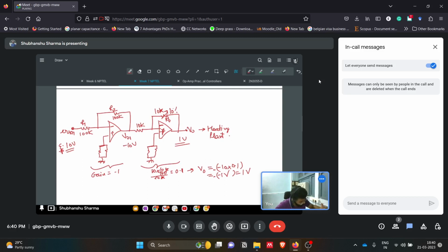So if we see, we have changed the sensitivity of the circuit. Initially, for 100 degrees Celsius we were getting a 10 volt range. But after using this attenuator, for a 100 degrees Celsius change, we were getting an output of 1 volt. Okay, so we got a new sensitivity here. This is the new sensitivity of our power controller, we can say system also.